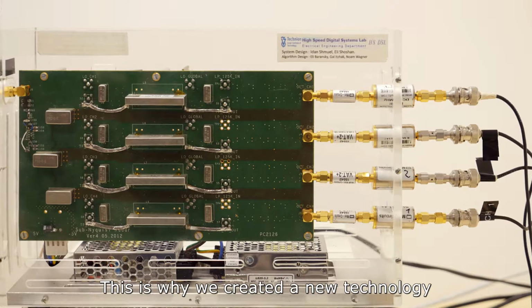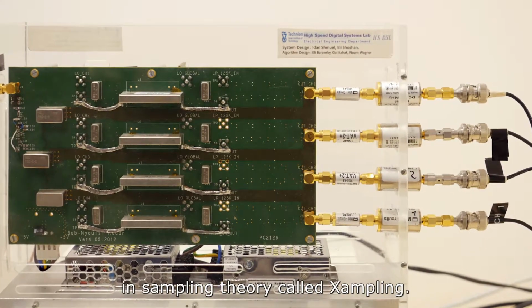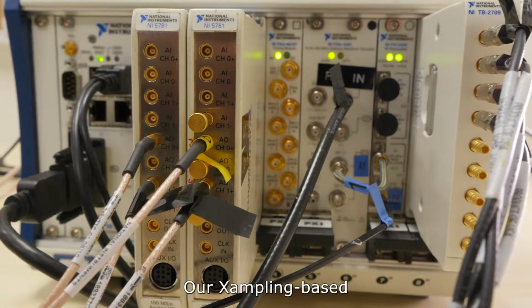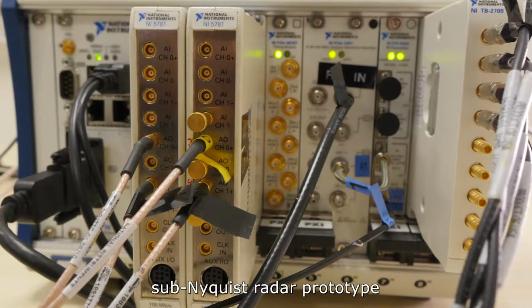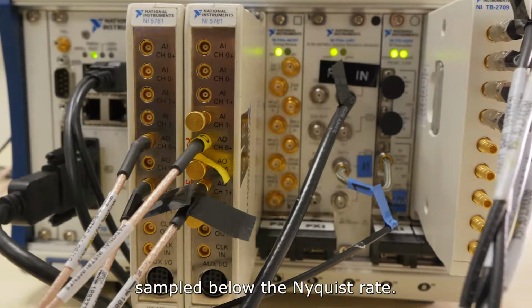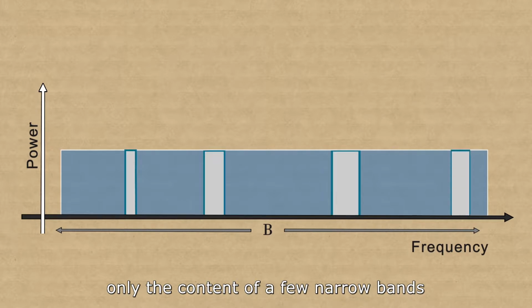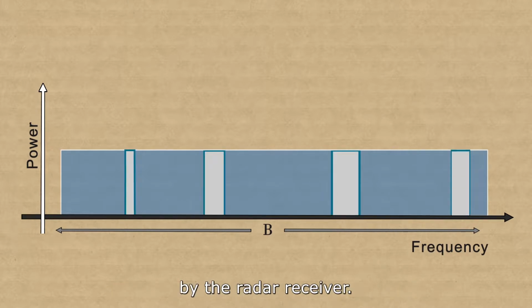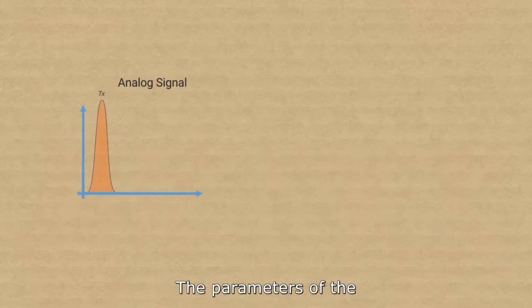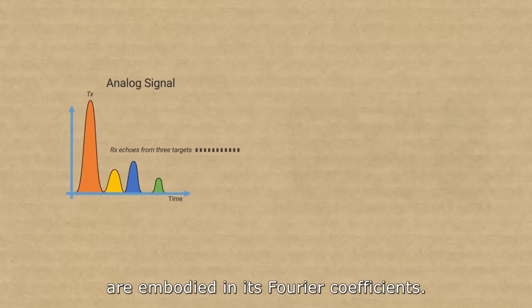This is why we created a new technology based upon a novel approach in sampling theory called Xampling. Our Xampling-based sub-Nyquist radar prototype detects targets using signals sampled below the Nyquist rate. In the Xampling framework, only the content of a few narrow bands is sampled and processed by the radar receiver. The parameters of the received analog signal are embodied in its Fourier coefficients.